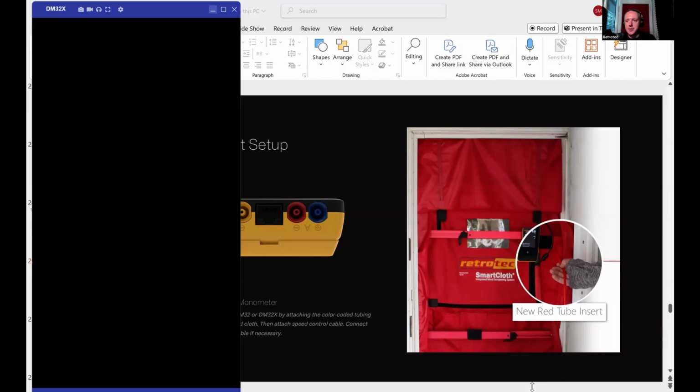Yeah, if that attic is supposed to be encapsulated and part of the conditioned volume, there are some quick checks you can do to see how well it's sealed up. If you just crack the attic door a little bit, and you have a smoke machine, a little handheld fogger like our air tracer, you can run the blower door. If it's sealed really well, there really shouldn't be any movement at the attic hatch. So just do some puffs of fog right there.